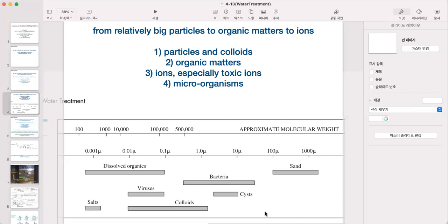Okay, so water treatment is a complex mechanism to remove all the organic matter, even if it is not toxic, but we have to remove it. Organic matter is very small, right? Very small. The colloid we can remove through the coagulation process. We are going to that in minutes, but organic matter is smaller than that. For colloidal matter, we use sizes in meters, micrometers, nanometers, and so on, but we don't use size in meters for organic matter. Instead, we use molecular weight.